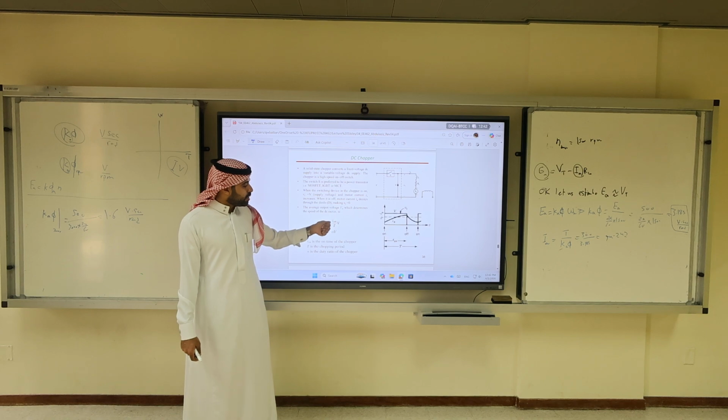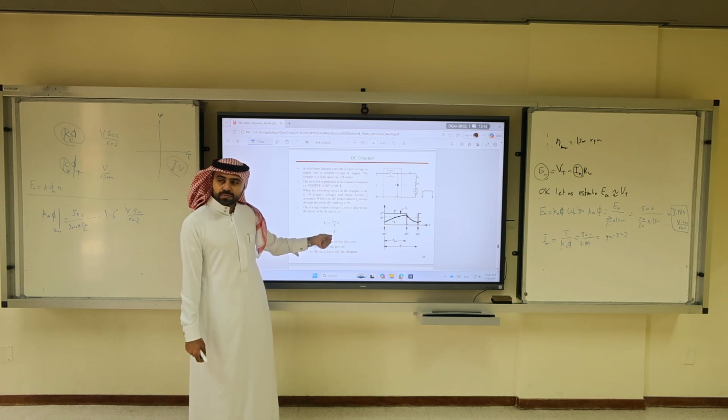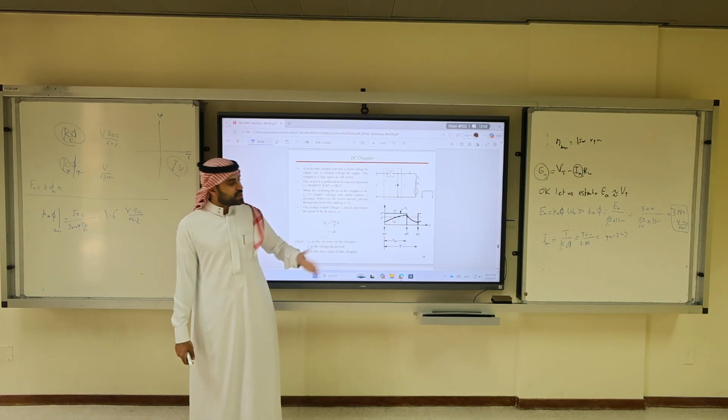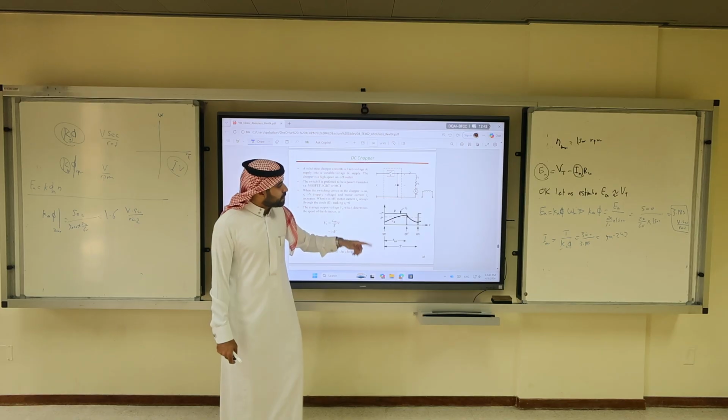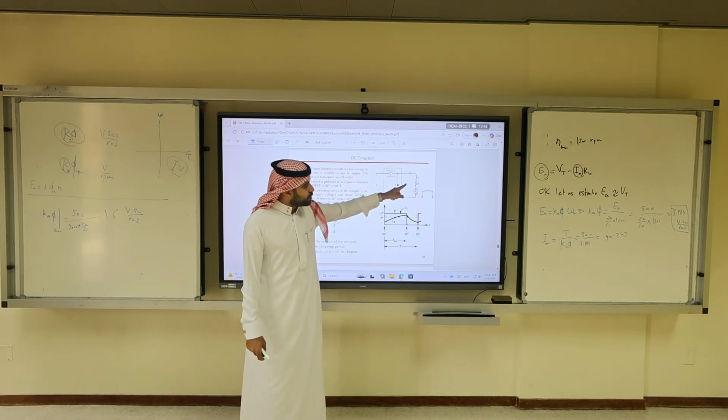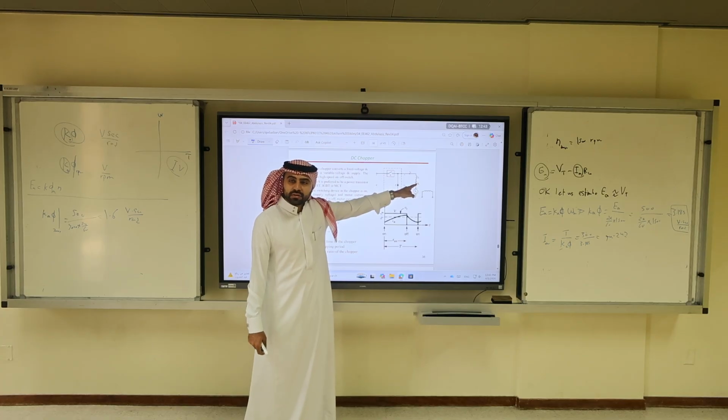So the time it's on over the total time is alpha V. If alpha is 0.1, then I have a reduction of the DC. So I chop the DC. This is simpler to operate. Keep in mind IA doesn't change suddenly because of the inductor.